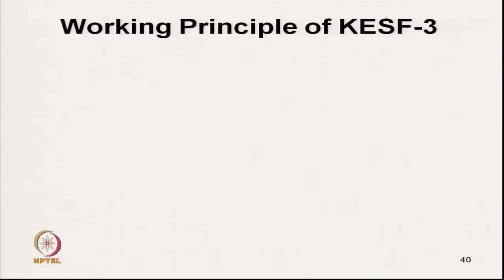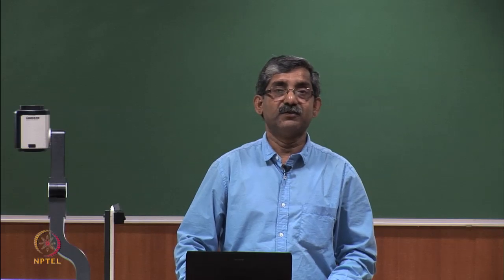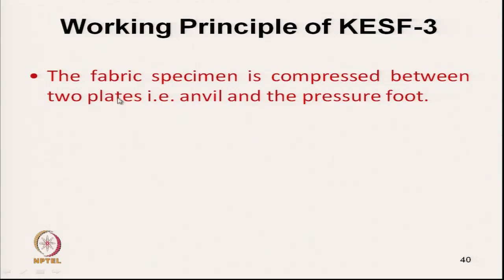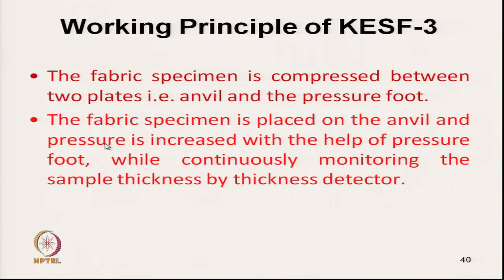Now, the next instrument is KESF 3, which is actually the compressional tester. The fabric specimen is compressed between two plates, one is the anvil, which is the support plate, and another is the pressure foot. The fabric specimen is placed on the anvil and the pressure foot is lowered. So, pressure is increased with the help of the pressure foot, while continuously monitoring the sample thickness by a thickness detector.